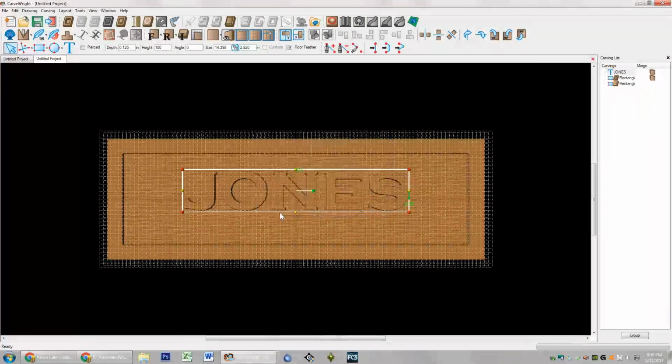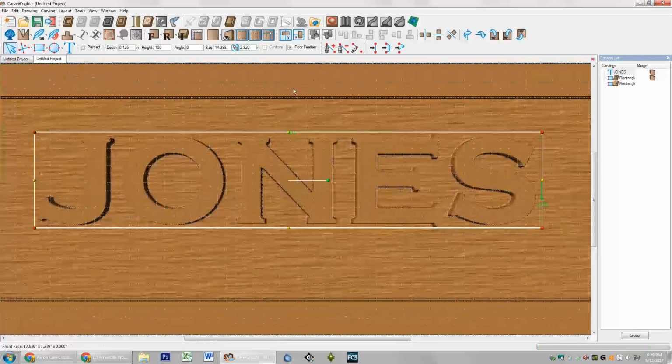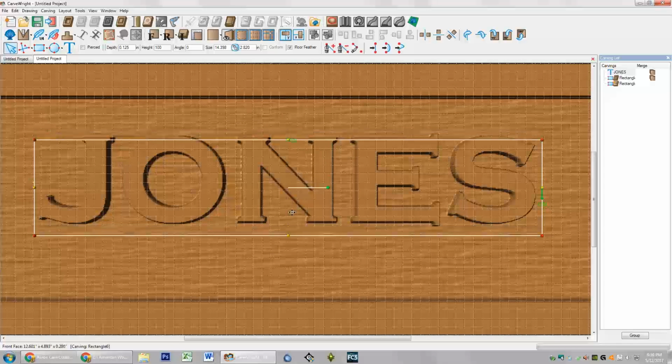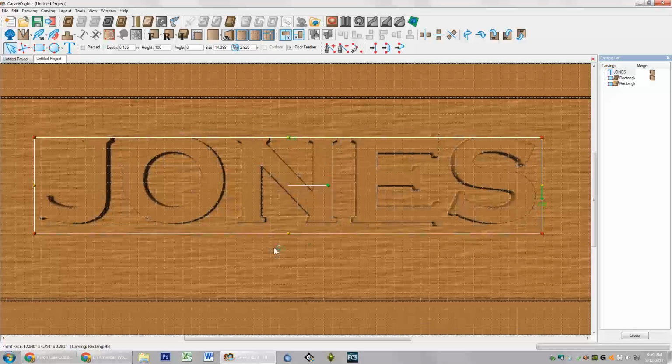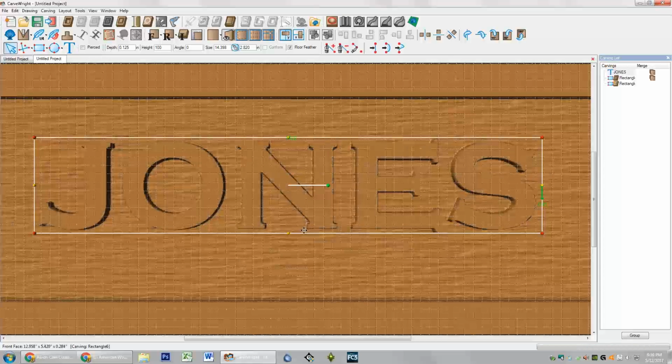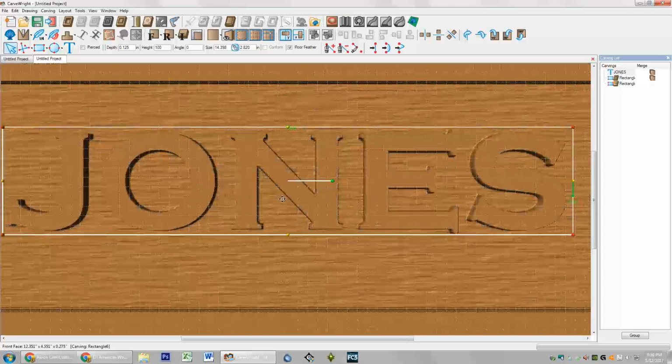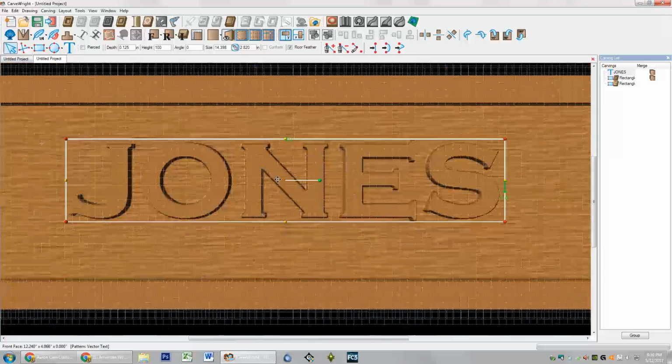Then I said OK, and that gives me a 1/4 inch grid, and this is going to snap either on the top line or this bottom line. It will snap on those grid lines. It'll also snap at the half line. So even though it's a 1/4 inch grid, it actually gives me 1/8 inch maneuverability. So between being able to snap the top line or the bottom line, I can also snap them to the 1/8 inch marks that you can't see, but you can tell when it's halfway between them. So it gives me a huge amount of maneuverability.